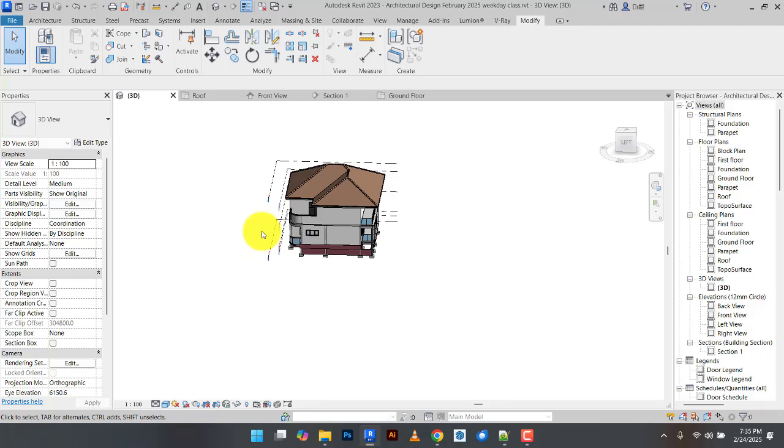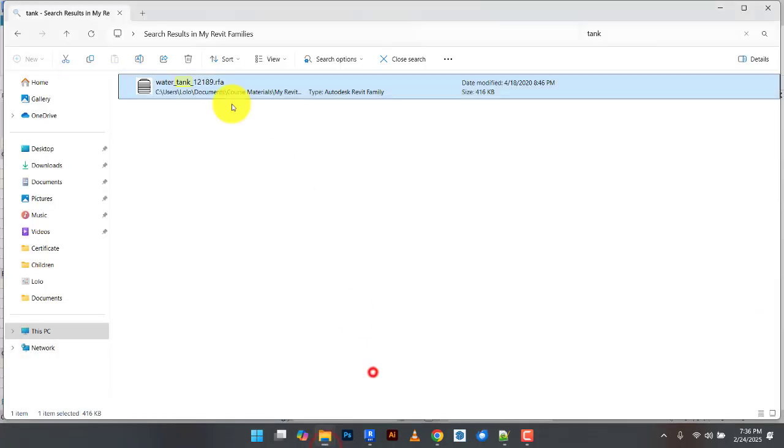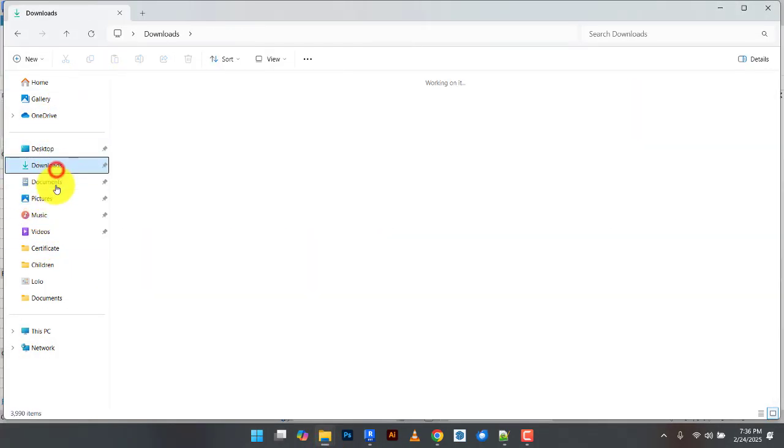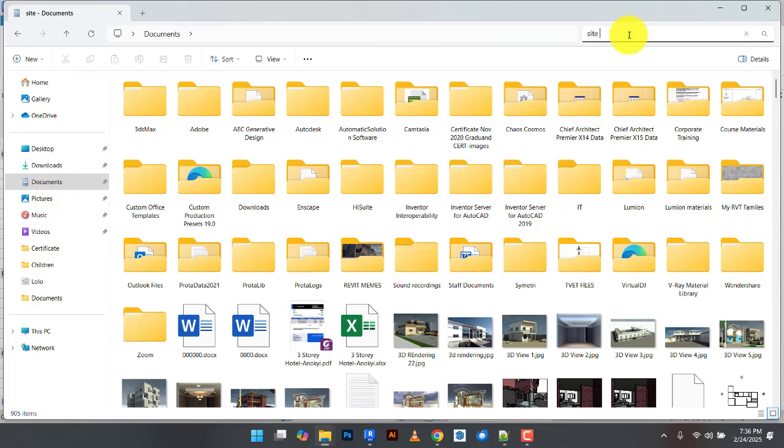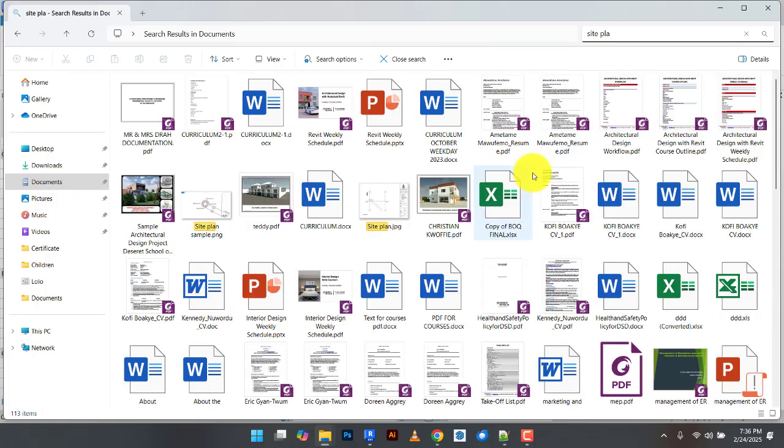So site design. What you're going to do is that your client will give you a site plan. The dimensions on the site plan, you're going to put them in the software to generate the exact size plan. Usually your site plan, your cadastral plan, comes with distances and bearings. So this is an example of a site plan. You've seen a site plan before, okay.